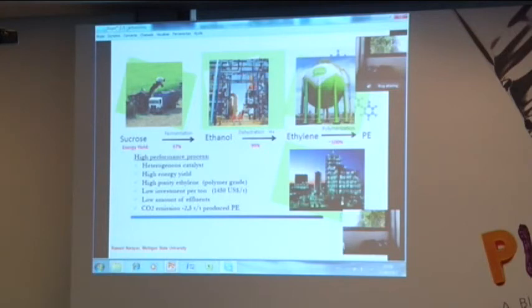They go from sugarcane to ethanol to ethylene, and immediately, as you know, for every 100 kilograms of biopolyethylene, they save 314 kgs of CO2. Of course, there will be additional CO2 savings if the process of converting this sugarcane to polyethylene is also sustainable and done right. You can see that that is their goal in the whole process. But fundamentally, that's the value proposition.